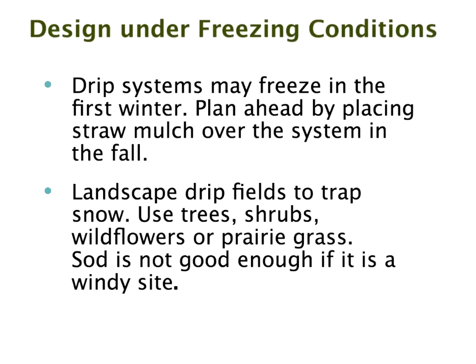And what's going to happen, though, is that your treatment plant's going to completely shut down. That's the more critical issue, and you really have to take the necessary steps with your treatment, according to your treatment plant, to get the anaerobic and aerobic digestion working as quickly as possible when you start up, because otherwise you're going to have pretty low quality water coming through, and you certainly will have to flush your pump tank and flush your filters as though you're starting up a new system after the winter.